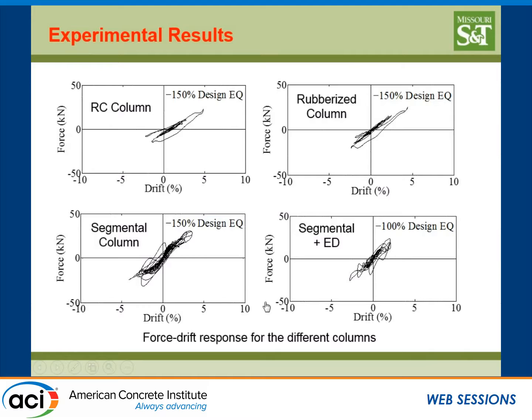This is the one with reinforced concrete, and we run the test starting at 10% acceleration of Rinaldi and keep going up until 150. And what happened at 150, we get rupture of the flexure rebar. Well, this is well designed, so the good news, it passed the 100% of Rinaldi and even went 50% beyond this.